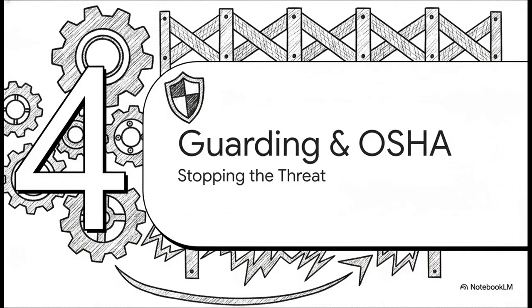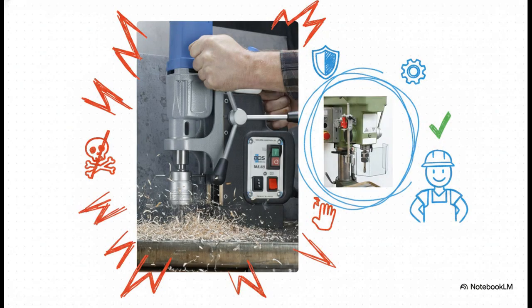Section 4, Guarding and OSHA Requirements. This is all about stopping the threat. Visually contrast these 2 setups. Look at the unguarded drill throwing dangerous, hot metal shavings right toward where an operator's hands would be. Now look at the safely guarded drill press right next to it, featuring a clean, electrically interlocked shield.